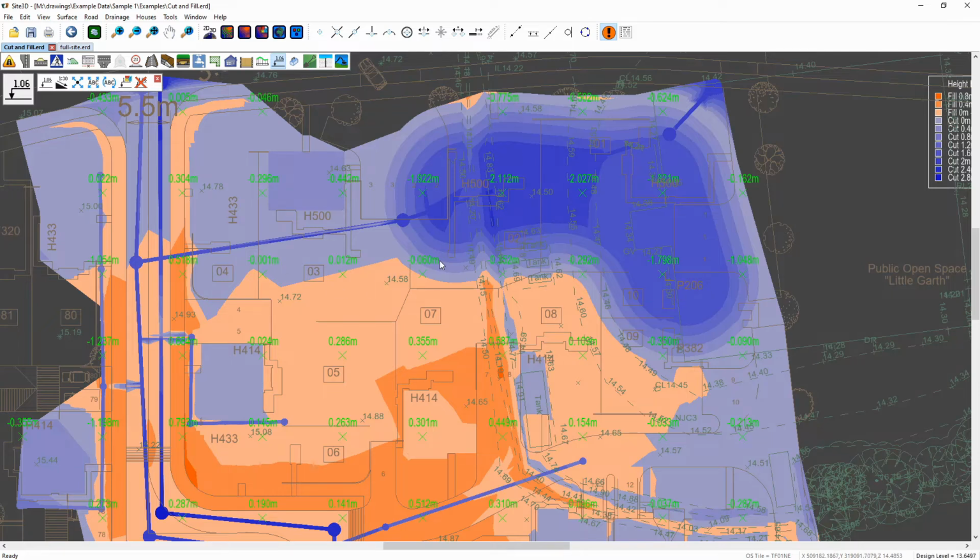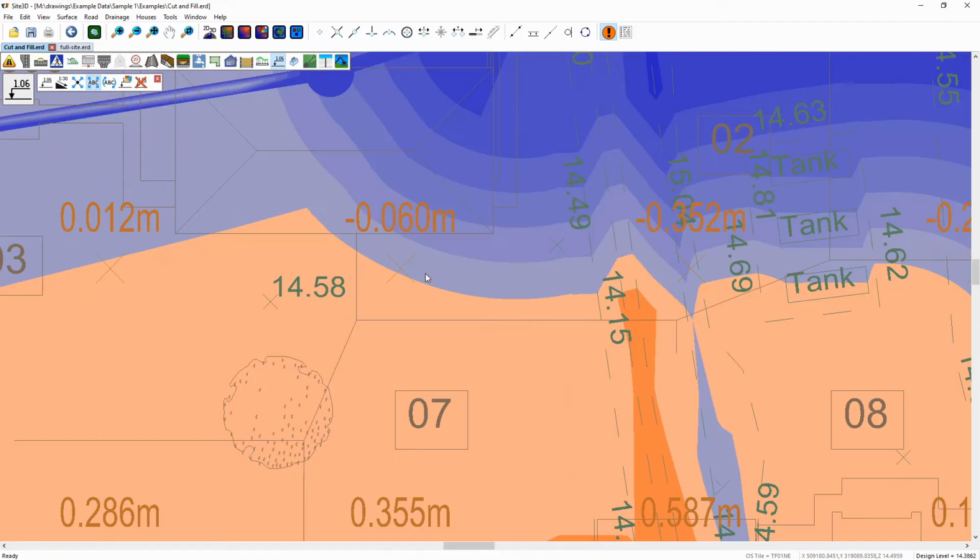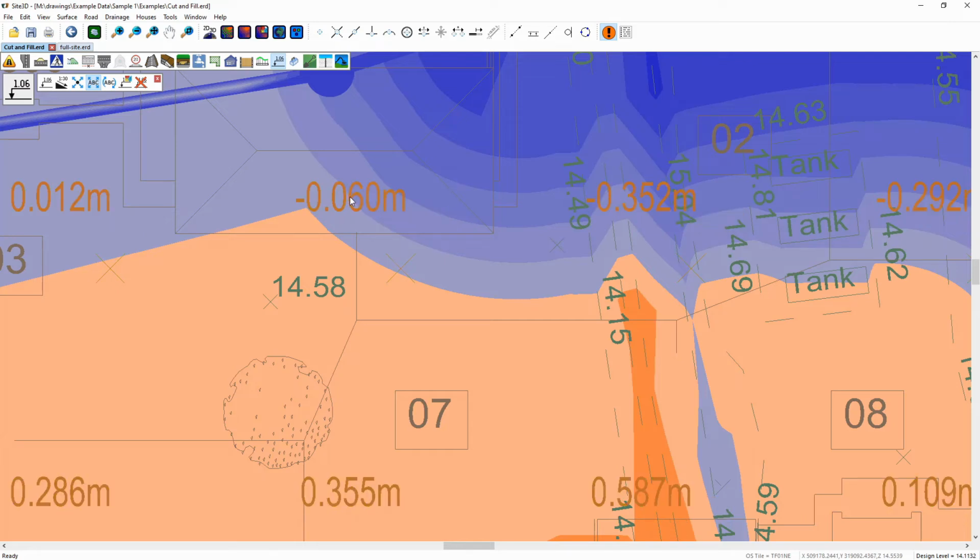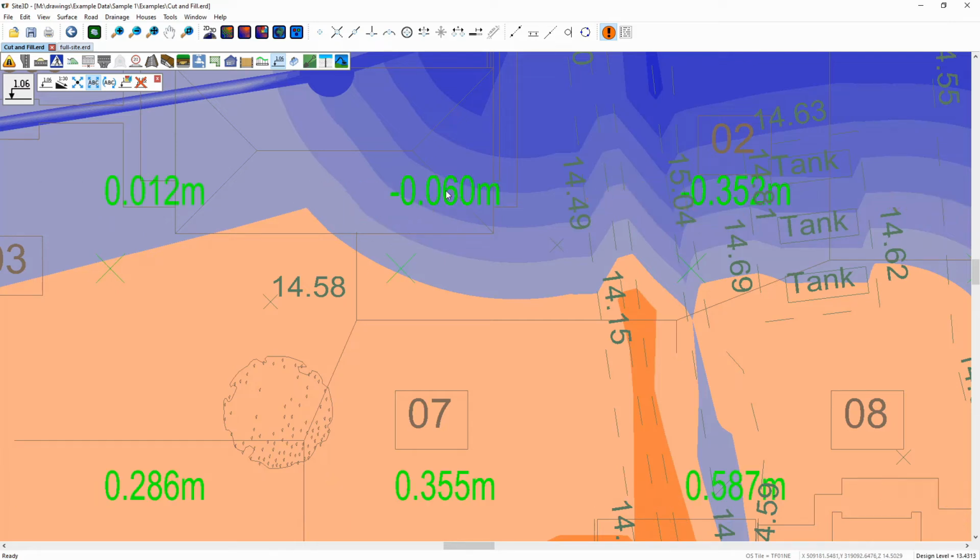If you want to, you can move a text and update all of the text positions relative to their positions in one go, and you can do that with the move annotation text. So I'm going to zoom in on one. If I click it and then move it around, you can see you're moving it relative to a particular point. As soon as you click, they all update as you go, and you can do that multiple times if you want to.